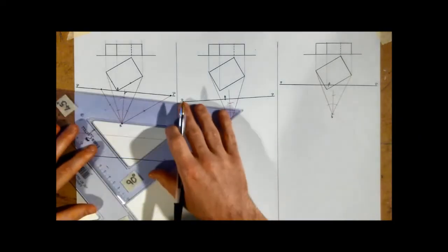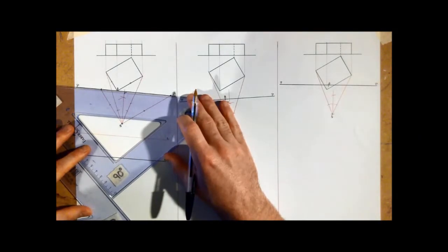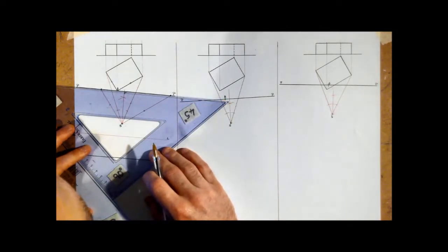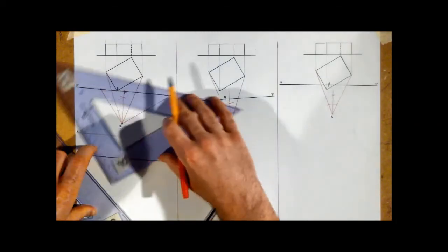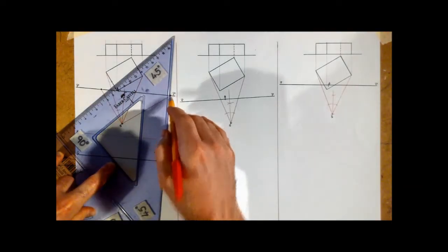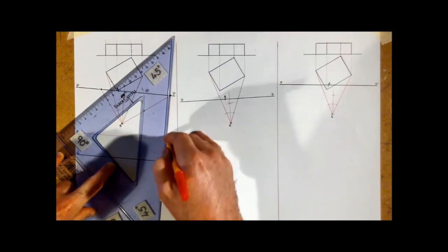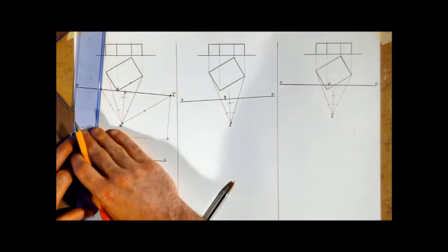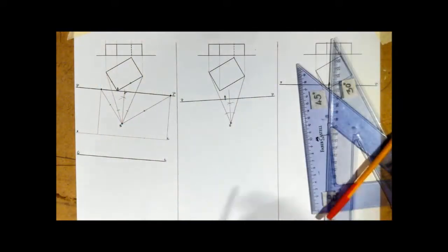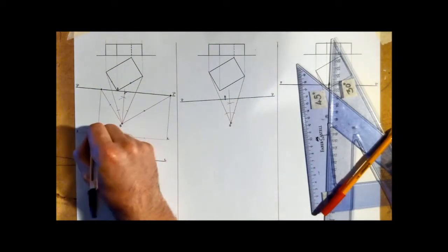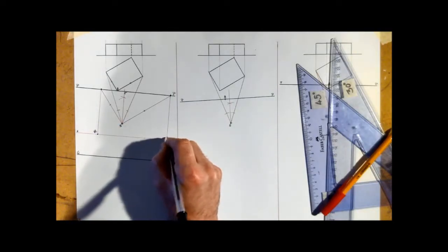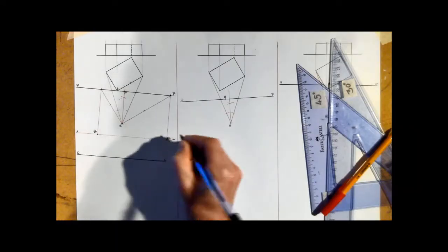So, as I said, perpendicular, this is quite easy. Literally line it up, 30, 60, or sorry, line up your 45 degree set square on it. Swivel it about. We've created a perpendicular angle here now. As you can see, 90 degrees. And what we have located in these two positions here is the positions of our VP1. And now I know it's to the L, so I'll actually just use that, and that is going to be VP2. I'll put the L out here.